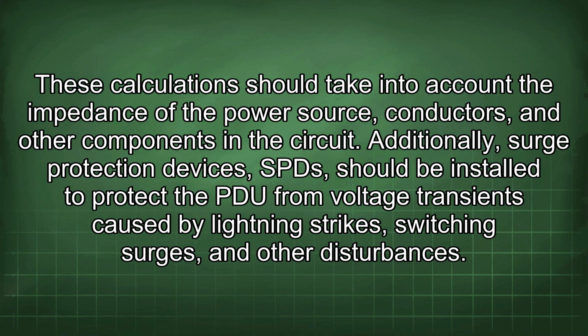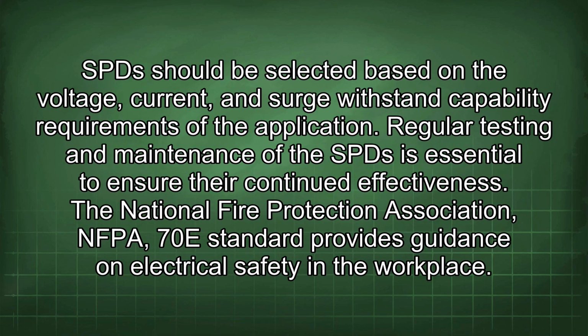Additionally, surge protection devices, SPDs, should be installed to protect the PDU from voltage transients caused by lightning strikes, switching surges, and other disturbances. SPDs should be selected based on the voltage, current, and surge withstand capability requirements of the application. Regular testing and maintenance of the SPDs is essential to ensure their continued effectiveness.